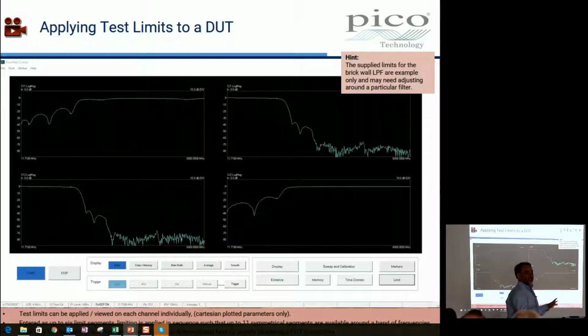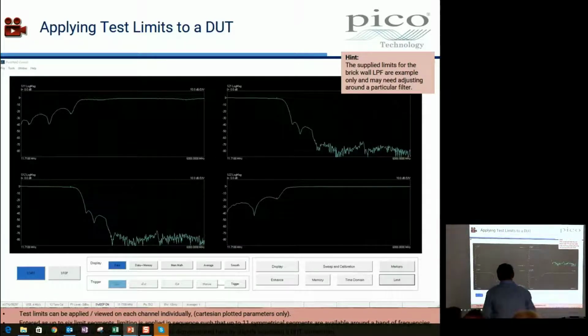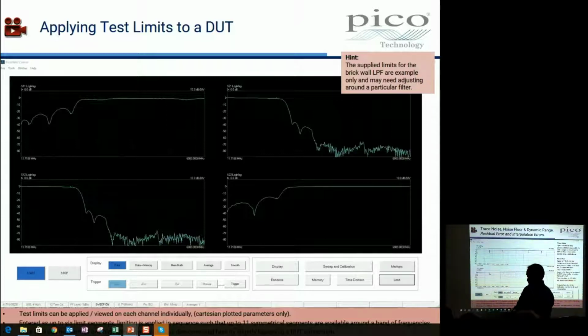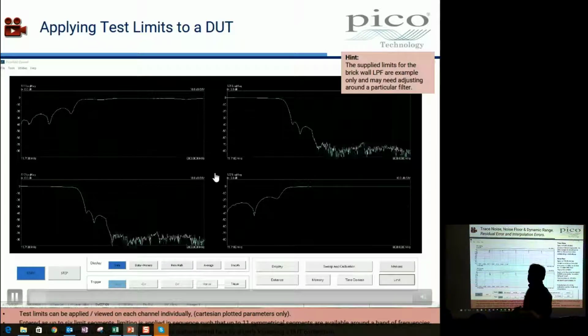So don't worry if it doesn't meet the limits, all the better in fact, because then you'll see the alarm. So you'll be proving that the limits test function works, right? But probably before you wanted to. But you'll see in this video how the limits are. So the noise you're seeing at the bottom is coming up to a maximum. It's peak noise, not peak to peak noise. You don't see the minimum as such on the log scale.